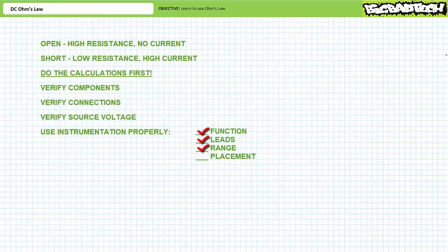Range. If your DMM is not auto-ranging, one must manually choose an appropriate range to obtain the most accurate measurement results. Whereas if your DMM is auto-ranging, your DMM will automatically pick the most appropriate range to obtain the most accurate measurement results. Related to range, be aware there is a limited range a meter can safely measure. Do not exceed this range or you will damage the meter and/or yourself in the process of doing so. Certain levels require appropriate levels of PPE, or personal protective equipment, to measure them safely.